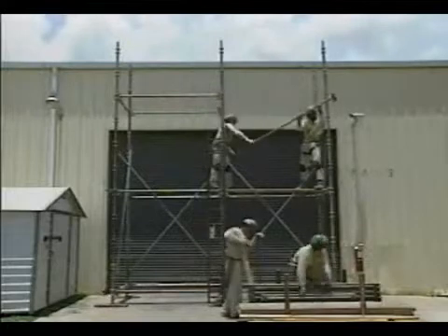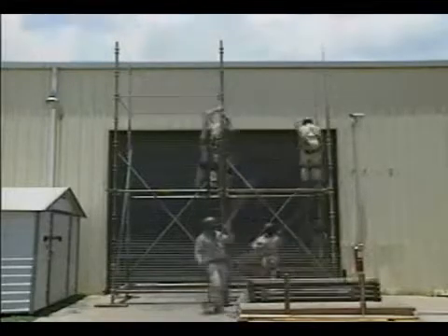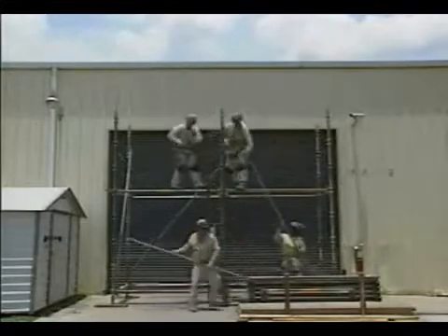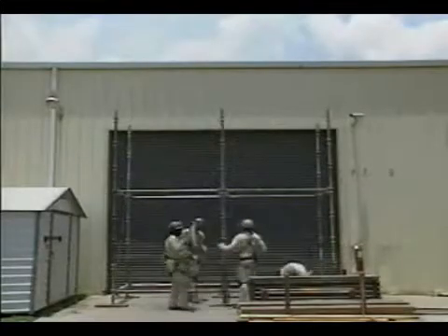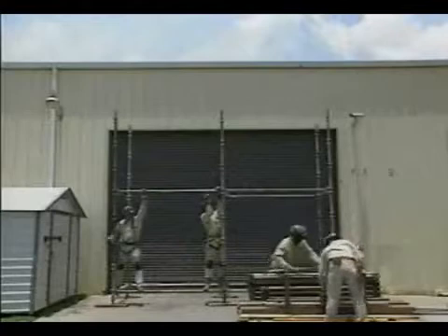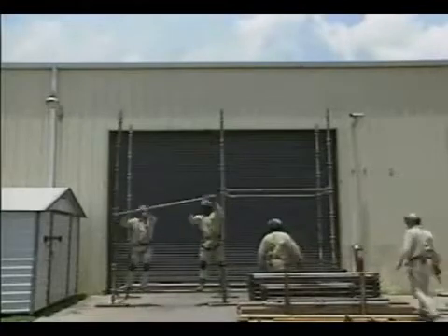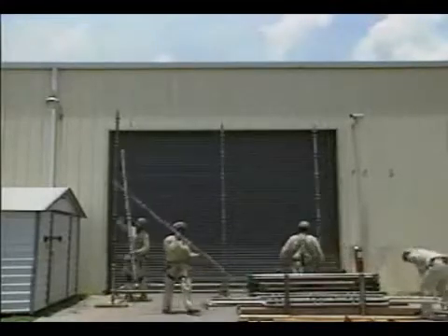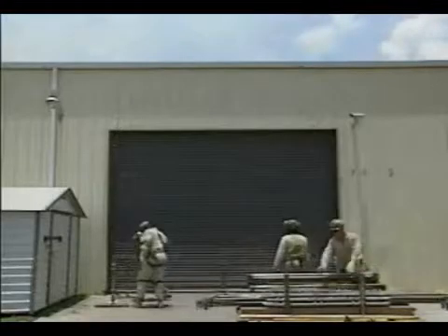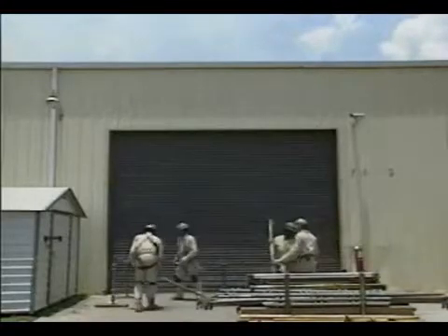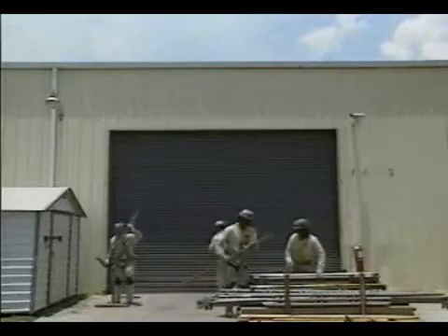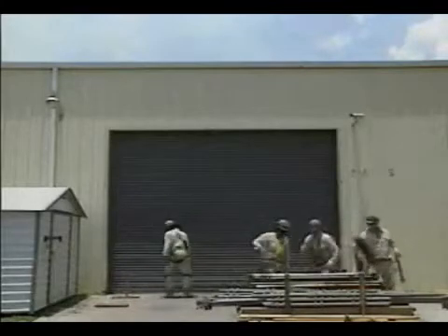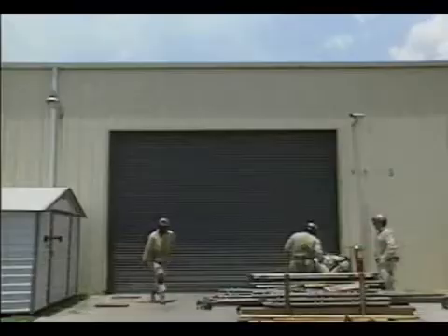Then the horizontal members that served as the floor supports are removed, along with the upper vertical legs. Next, the diagonal braces are removed from the vertical legs, and the ladder is taken off. The horizontal members that were connected to the midpoint of the first set of vertical legs are then taken down, and the vertical legs are lifted off of the starter collars. Once the lower horizontal members are removed, the starter collars are lifted off of the screw jacks. The screw jacks and base plates, along with the wooden sills, can then be removed to complete the disassembly.